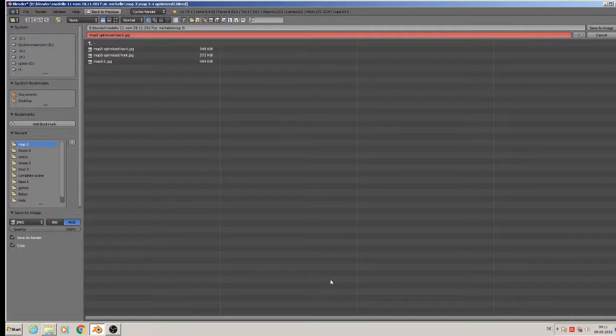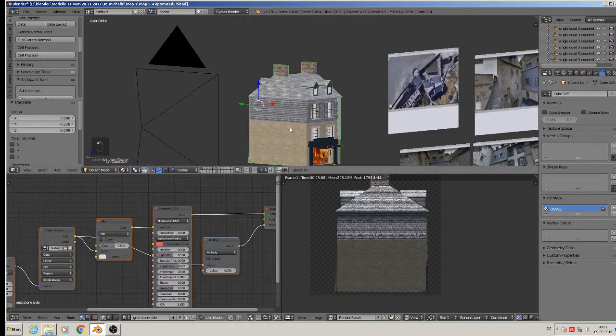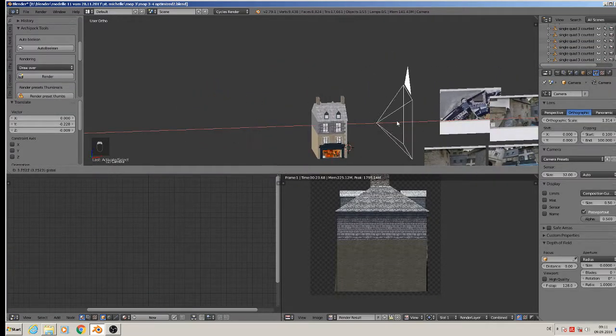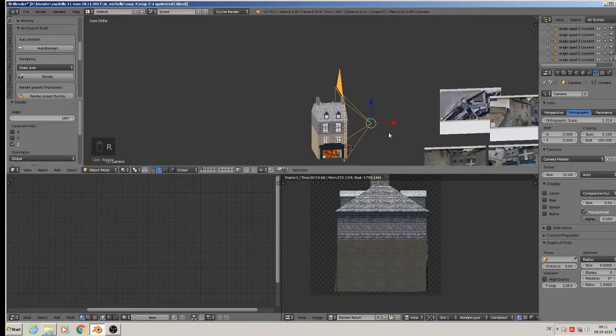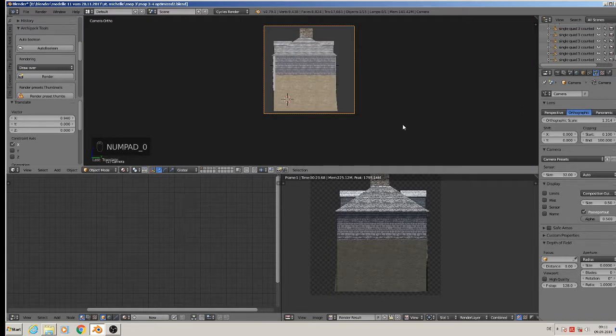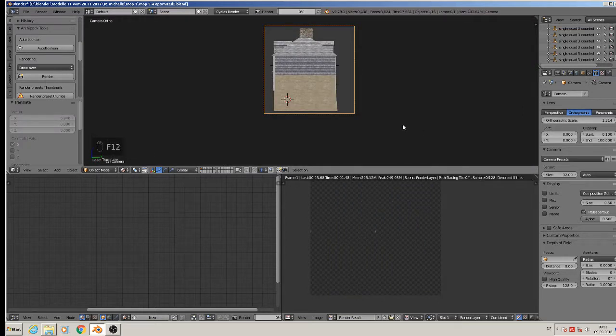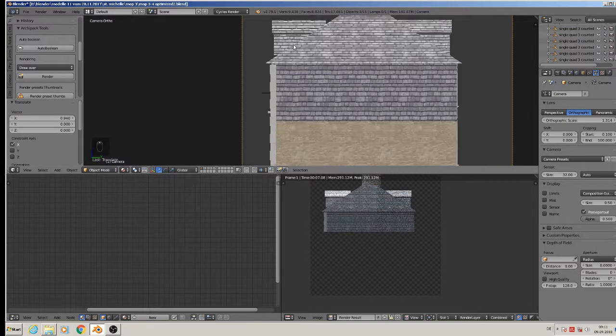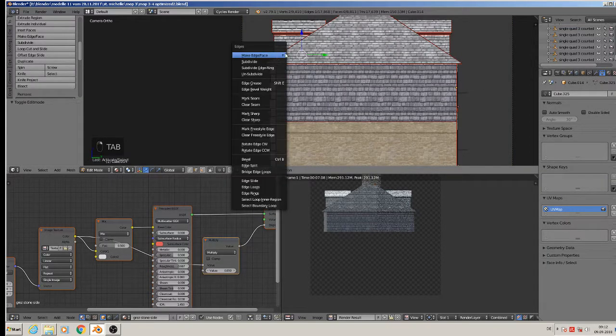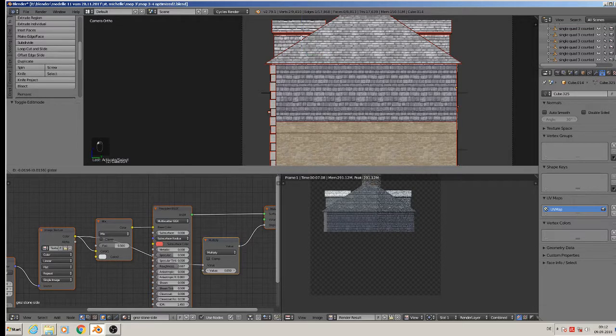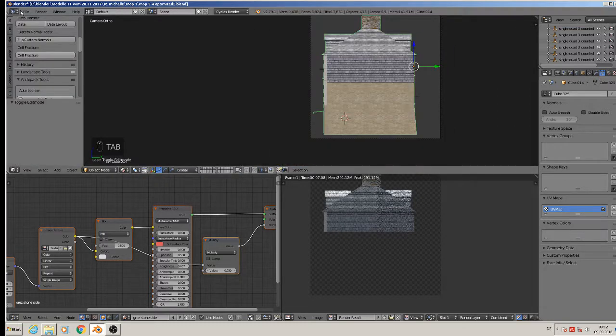So image save as left. Save as. Then move the cam to the other side, rotate set 180 degrees, bring it a little bit to the X, numpad 0, and render. Stop. That here is not good. We should take here this part deeper, that part more to the rest there. Okay, file, save, render, F12.